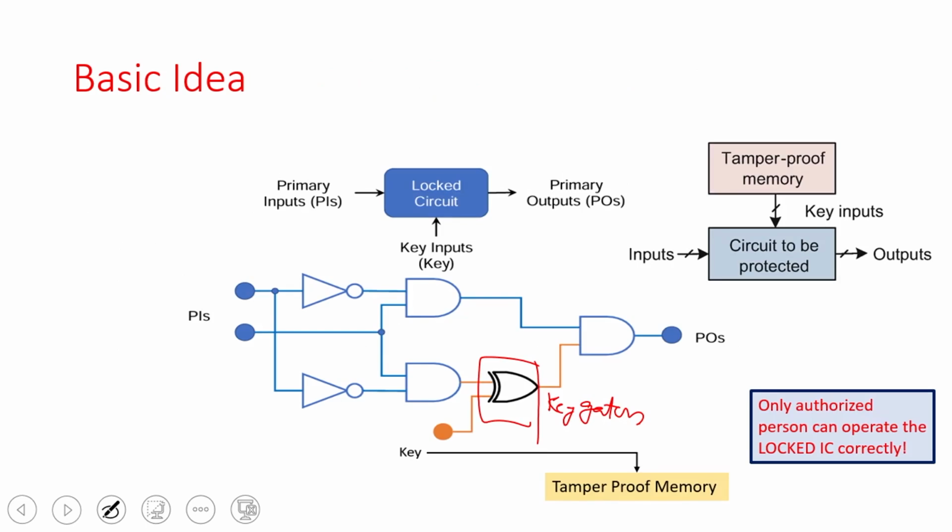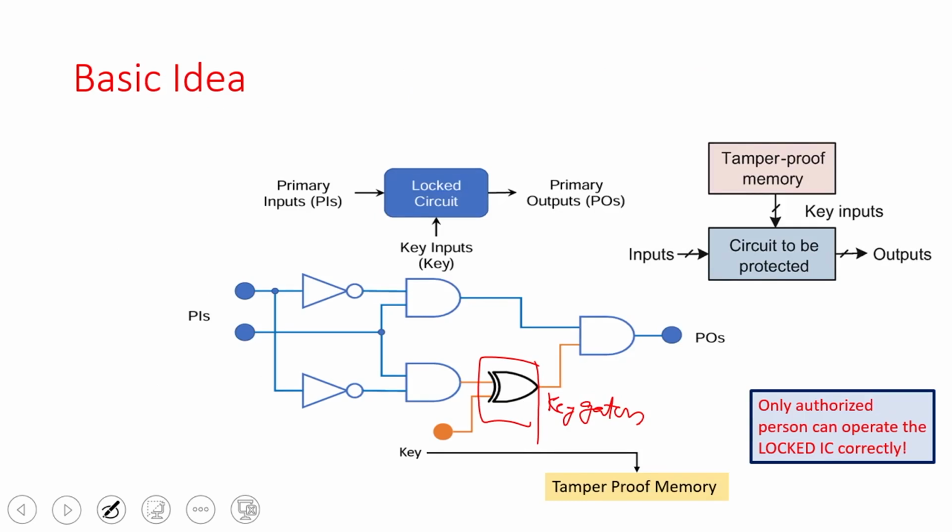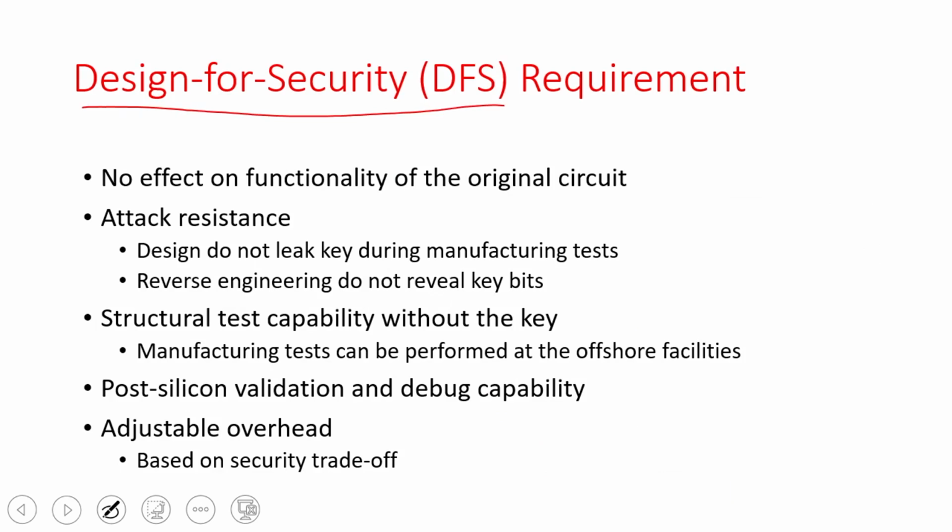I will talk about various different techniques, but what are the design for security requirements, right? Whether you use an XOR gate, XNOR gate or mux, what are the things you have to ensure? You have to ensure no effect on the functionality, in the sense that if you give the correct key, it will 100% of the time give the correct output.